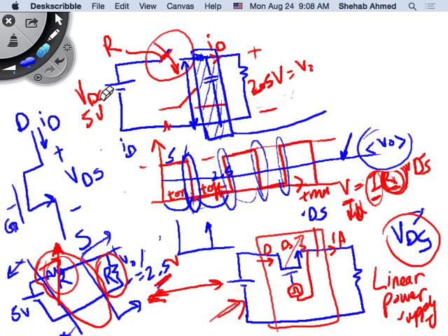So this is also an important consideration. It's called duty cycle. It's the time that the switch spends on, so that's the switch's on-time duty cycle. Or you can calculate the switch's off-time duty cycle, depending on what I'm asking for. If I ask for the on-time duty cycle, it's this T on. If I ask for the off-time duty cycle, it's the T off. Duty cycle is a portion of the full cycle time.